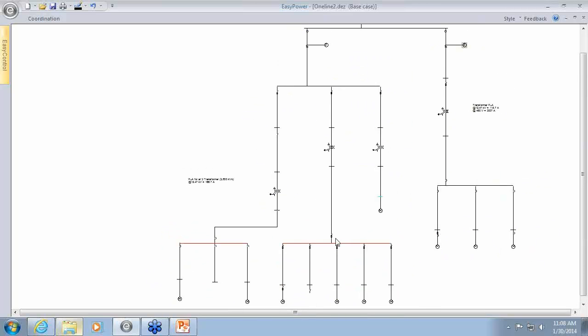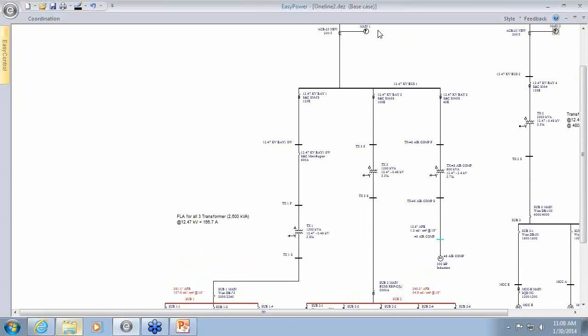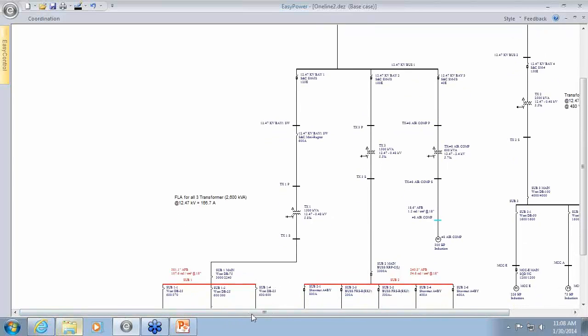They wanted all the transformers to be running, but when maintenance needed to happen, the energy needed to be lowered. So the maintenance mode was set based on the full load amps of all the transformers, but was set low enough that the maintenance mode setting would apply to the estimated arcing current at each of these equipment.